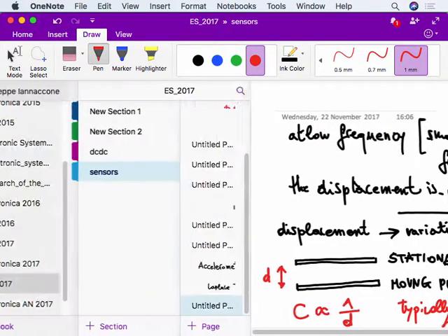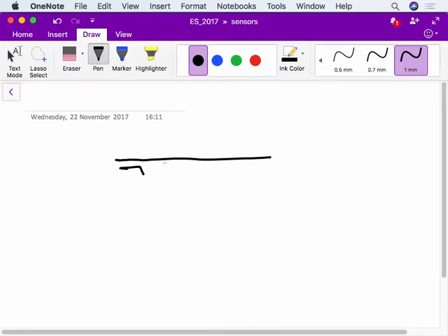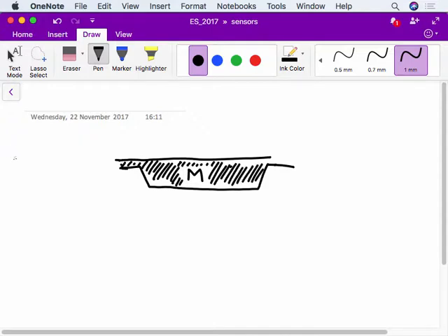How does it work in practice? In practice, this is all done with silicon technology. This mass is a membrane. The typical implementation is that this mass is done with a membrane. So this is made of silicon oxide, which is obtained with a technique that is called micromachining. It is a technique which uses the typical silicon technology. So this is, let's say, the lateral view.